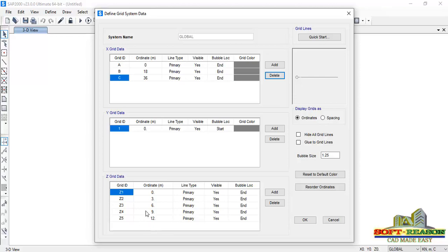For the height, from 0 we will add a height of 6 meter, and then for the arc, we are considering a curved beam, so the radius is going to be 2.5. So 2.5 plus 6, you are having 8.5 meter, just like that. Then for Z5 and Z4, we are going to delete those, so we'll be left with this. If I should activate spacing now, you will notice that you have 18.